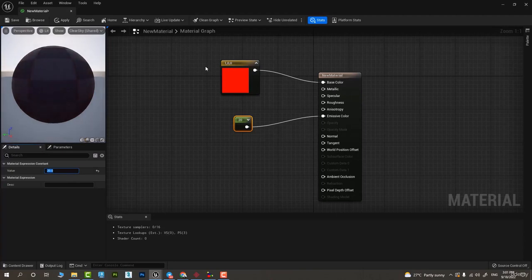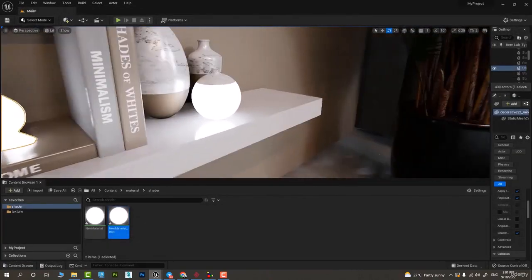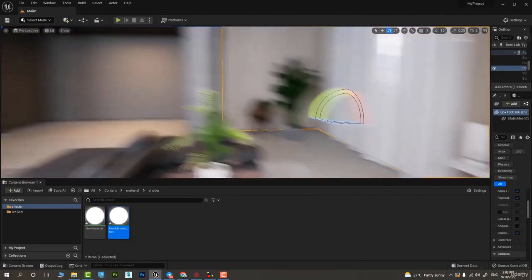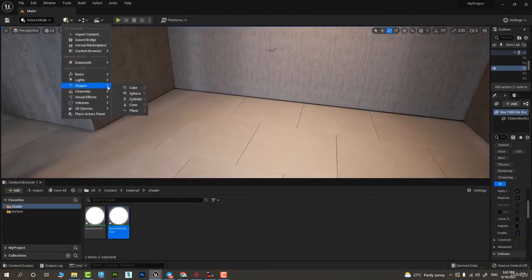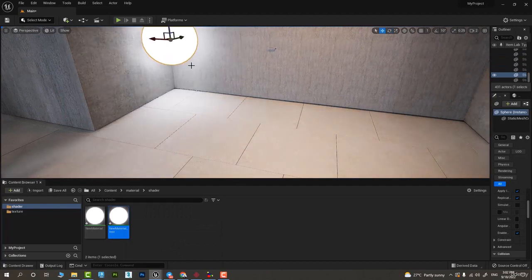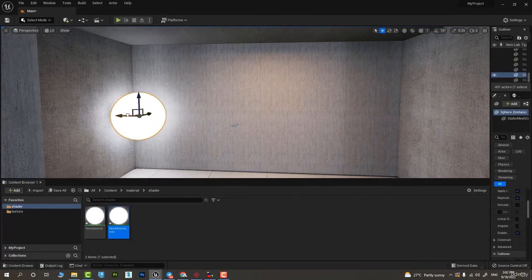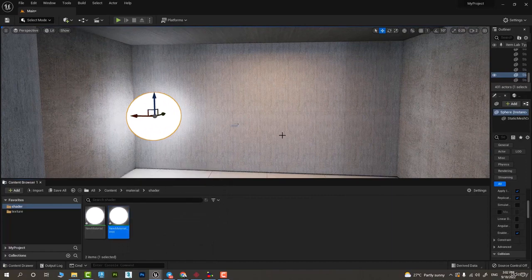And if I put it at 20, you can see how much light is emitted from this object here. So I apply it, go back to our main, see, they are almost resembling a source of light, and they're emitting a lot of light from them. And now if I put a similar material in a darker place like this place, and I apply this emissive quality to it, you can see how much light is being emitted from this object.